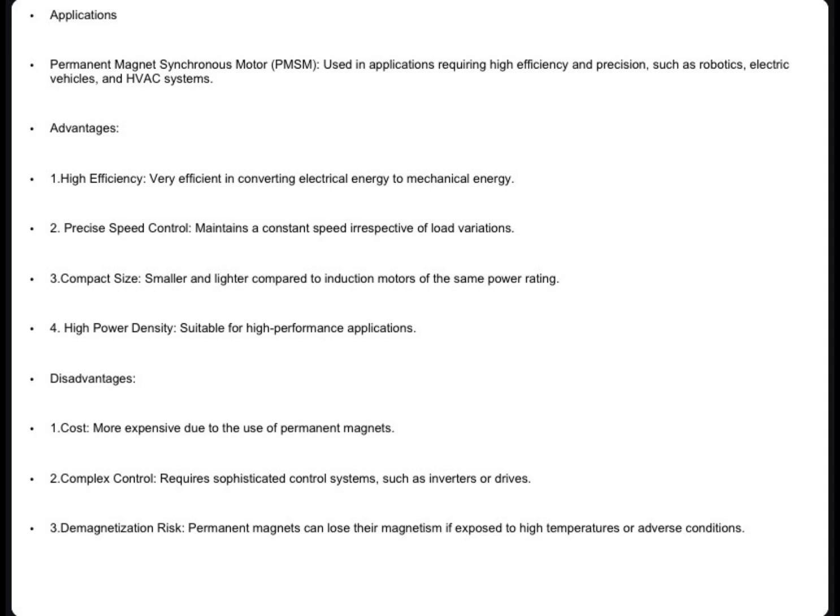Disadvantages. 1. Cost. More expensive due to the use of permanent magnets. 2. Complex control. Requires sophisticated control systems such as inverters or drives. 3. Demagnetization risk. Permanent magnets can lose their magnetism when exposed to high temperature or adverse conditions.